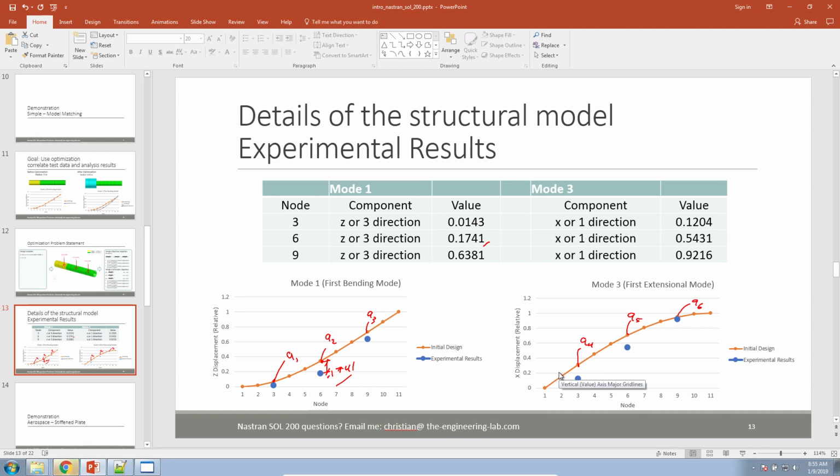So suppose mode 3 suddenly jumps to mode 8, but the optimizer thinks, okay, I have to focus on mode 3. If mode 3 jumps to mode 8, but the optimizer is still focused on mode 3, it's lost tracking the actual mode. So what mode tracking does is make sure that it follows the mode. So if mode 3 becomes mode 8, the optimizer knows to switch from 3 to 8 also.